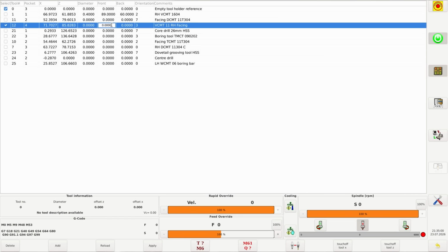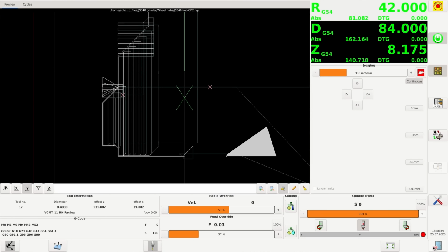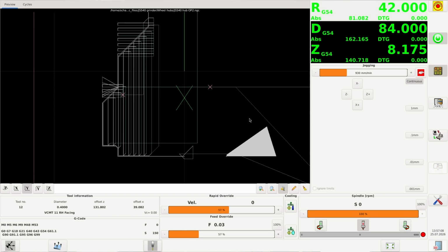That tool number 12, and see if I can edit this and have it keep something. See, now it's saving the value. Brilliant. Tool number 12 is an orientation 3 with a 35-degree tip, and that's then correct. It's got a 0.4 millimeter nose radius. Those corrections I made are obviously now working. Thanks for your help, Sierra.